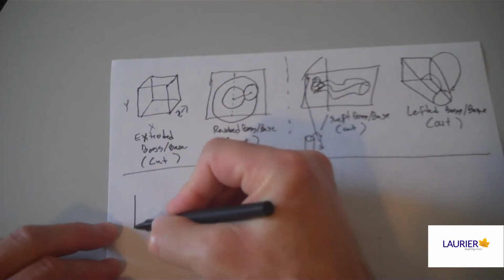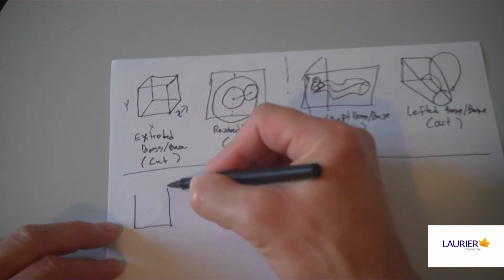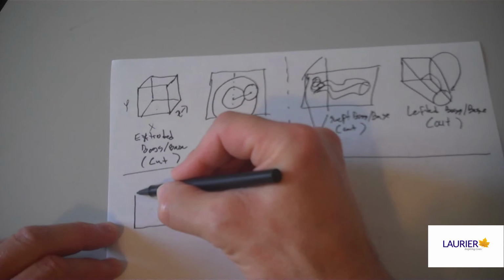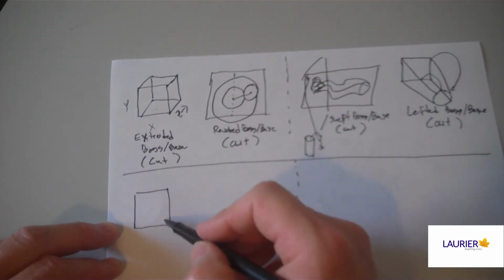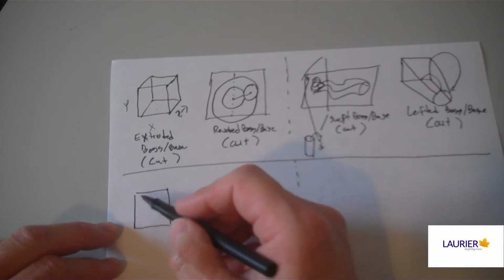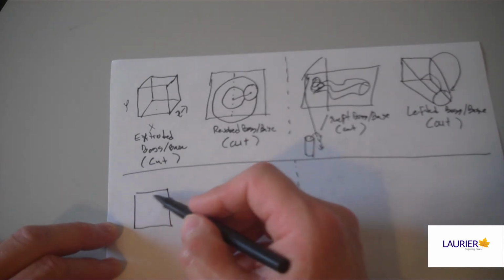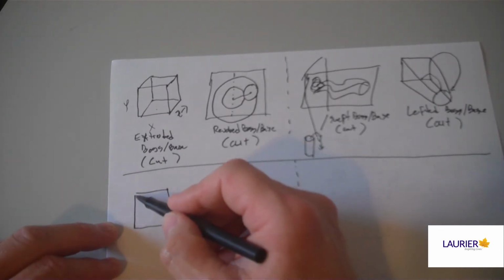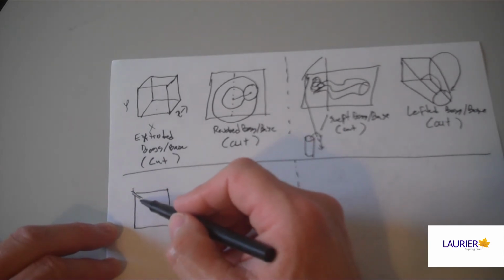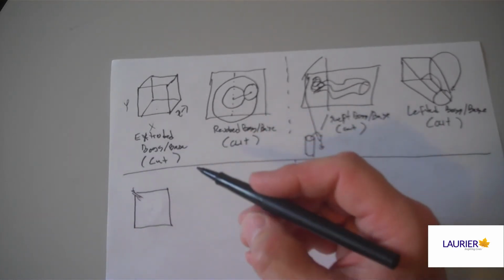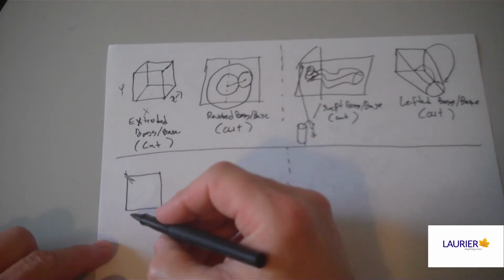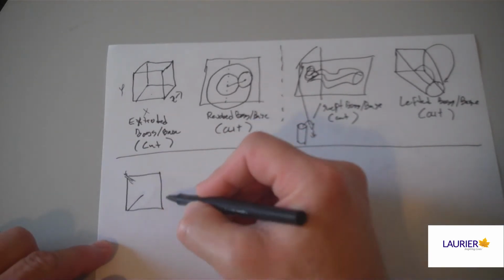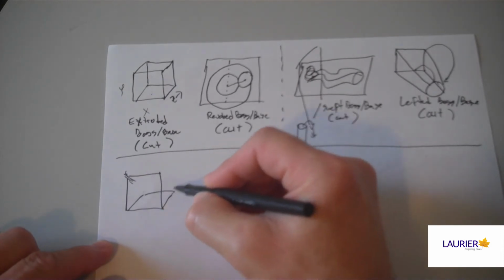The first version of this type of failure that we're going to cover is when we've got a square or any other shape and we haven't quite closed it up. If we think of this as an area, well, we haven't enclosed that area. If this was a sheep pen, the sheep could sneak out and run away here and do whatever sheep do when they get out of the pen. The non-farming problem here is that when we extrude that shape along the z-axis, because it didn't capture an area in 2 dimensions, it won't capture a volume in 3D.